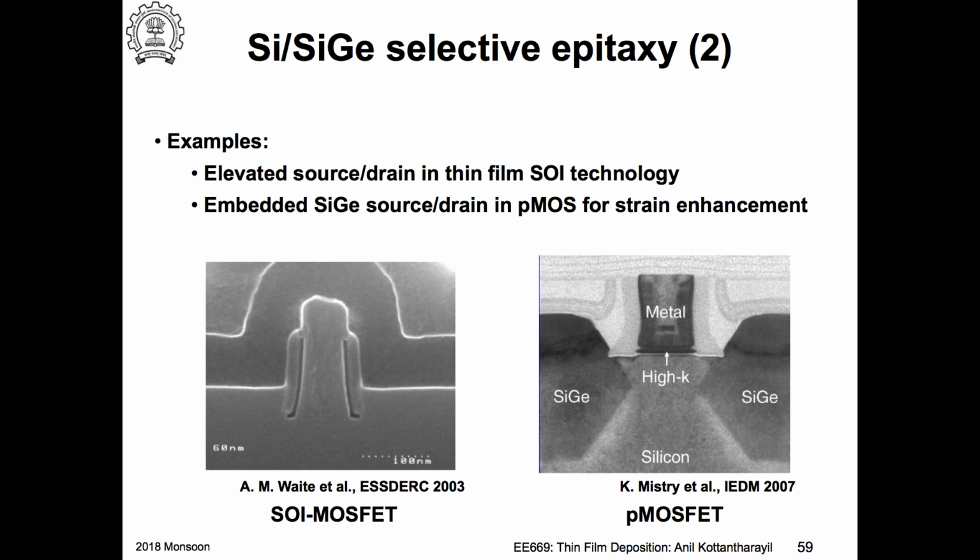This is an example where you can see your transistor. In the last slide, why don't we mask the other regions and then do the deposition? The problem is, you look at this. This is my transistor. This is a gate. I want to mask this tiny thing there. These are very small dimensions. If I am doing a masking, I already mentioned there is something called alignment. So I will have to leave a lot of space to account for that error in alignment.